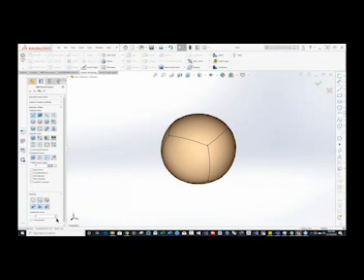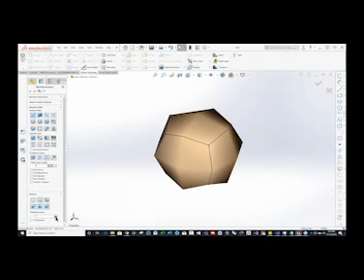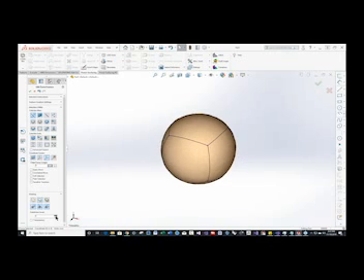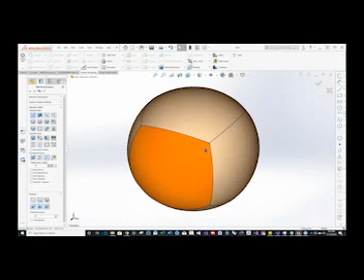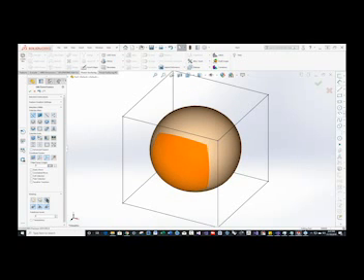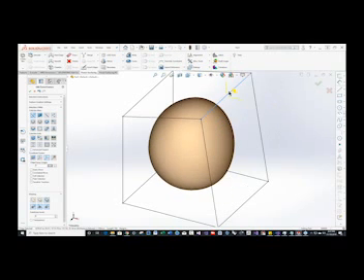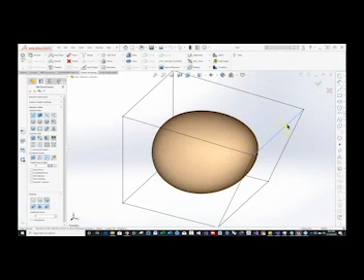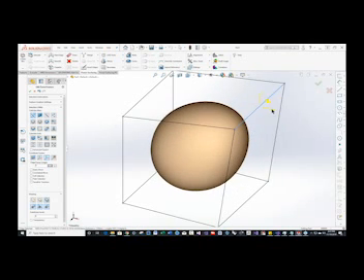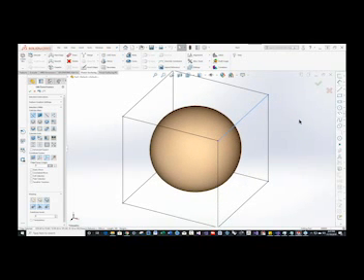So it's been subdivided, and we can control the number of subdivisions for display purposes. Typically we work at 3 or 4, which gives you a very nice smooth model. And you can also use the cage mode, which shows the control polygon on the outside. Now, one way to think about this object is it's kind of like a soap bubble, that these things pull on that soap bubble. And as you move the cage around, it pulls towards that soap bubble. And so that's a good analogy to think about it.